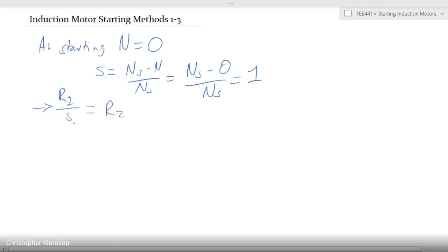This is very key, because this was representing the amount of air gap power that was moving across. So all the air gap power is moving to the other side. The slip is 1, so this value is what is being passed through in the rotor. That means that the current within the rotor is much, much higher than the magnetizing current.